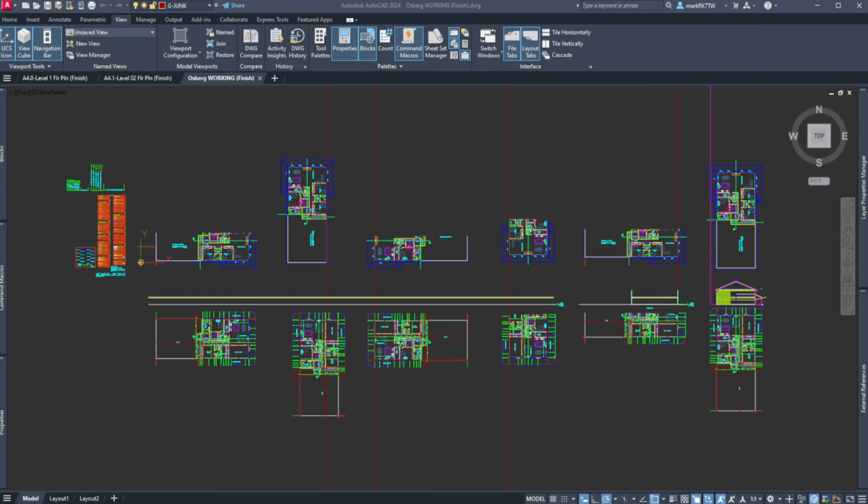So what I've done is I went into my international residential code, and we're on 2021 here. I just typed in the word rise because I'm pretty familiar with the code. I just looked for terms, and I have found that searching with one word is the best way to find things in this code book. So vertical rise is going to be the entire rise of a flight of stairs, but it's going to get me right in the area. So I'm going to click on this one.